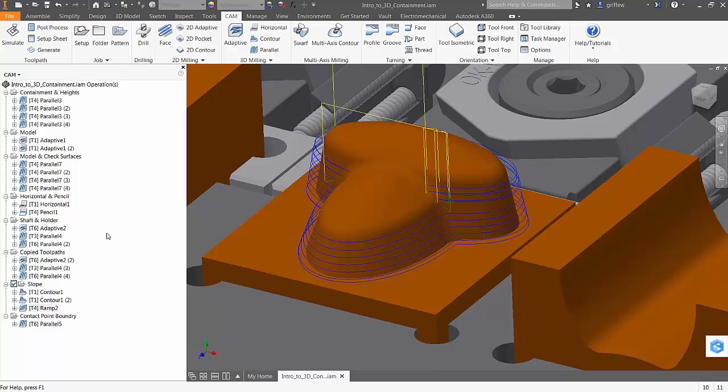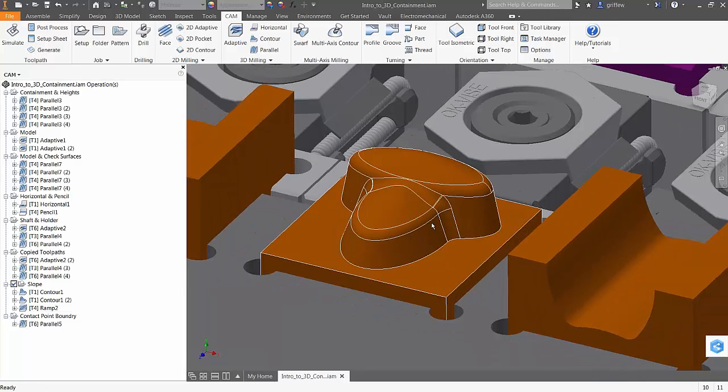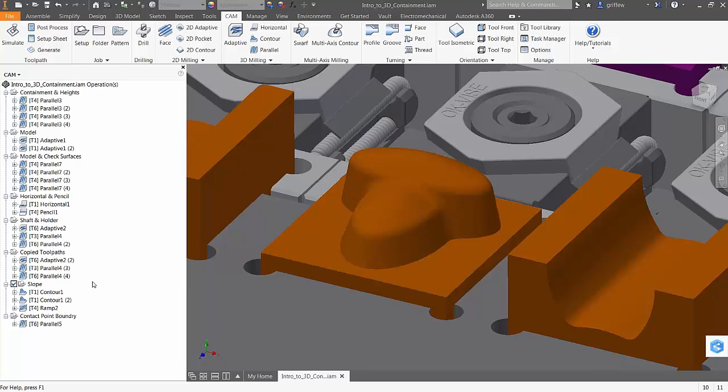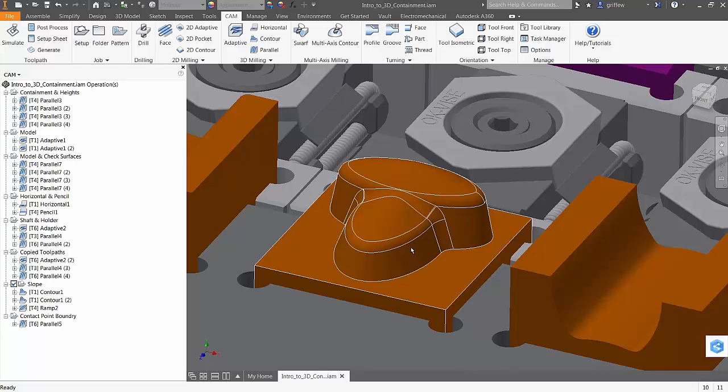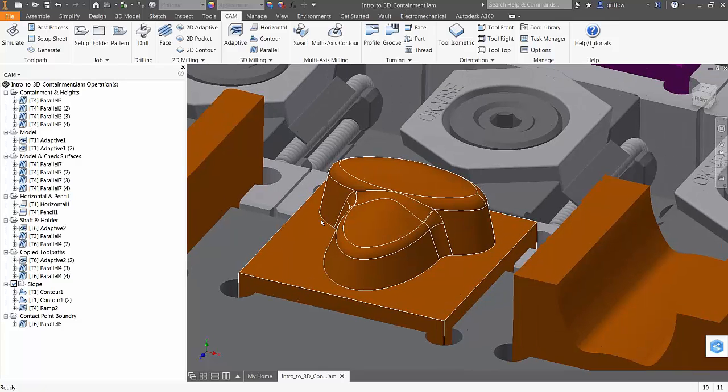Looks like it says when I use the ramp, with the same settings, it generates 3 to 4 times more lines of code. Why is that? That's a good question, Ben. Because we're getting also Z moves in there too. So as you're using a contour, it's only looking at your X and Y coming out, moving down in Z and X and Y. So when you're using the ramp, you're getting all three axes. In other words, you're using the X, Y, and Z simultaneously.